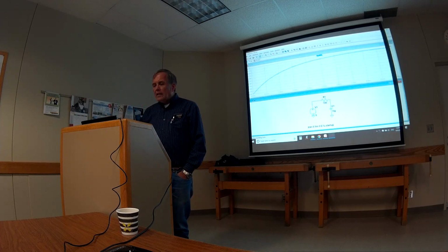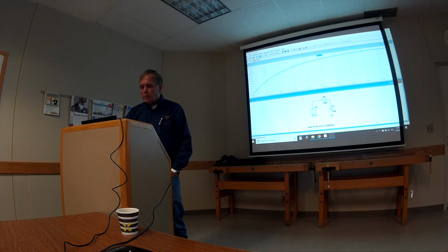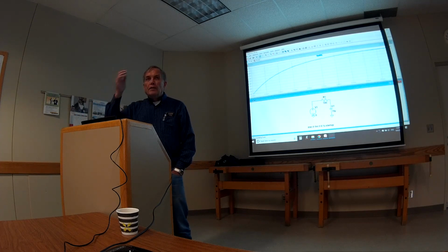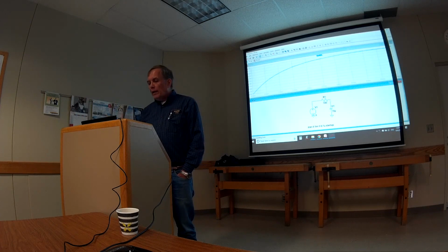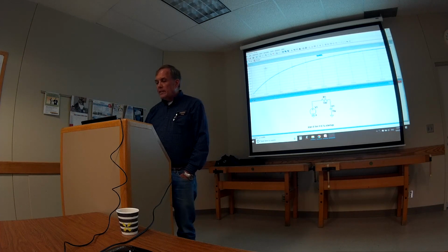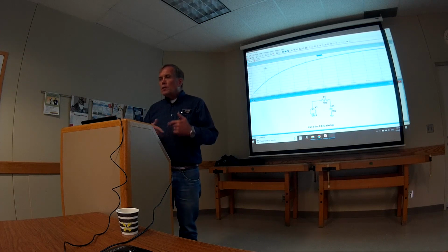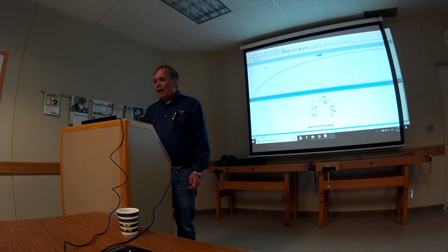Okay, now the thing to look at here, obviously, is it's showing how the voltage on the junction between the resistor and capacitor is charging up to eventually get to 5 volts when the capacitor is fully charged. Now, the thing you think about with a capacitor is the time constant, RC. If you multiply R times C, 100 times 10 to the minus 5th, so 10 to the minus 3rd, 1 millisecond should be the time constant. At one time constant, it's going to charge to approximately 62 percent of the full value.